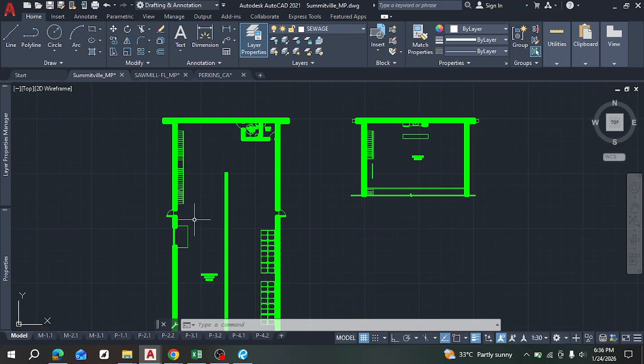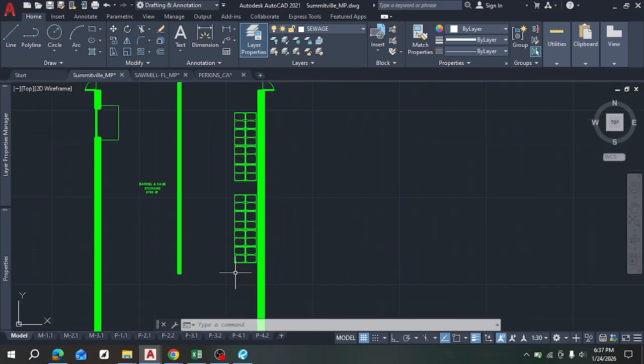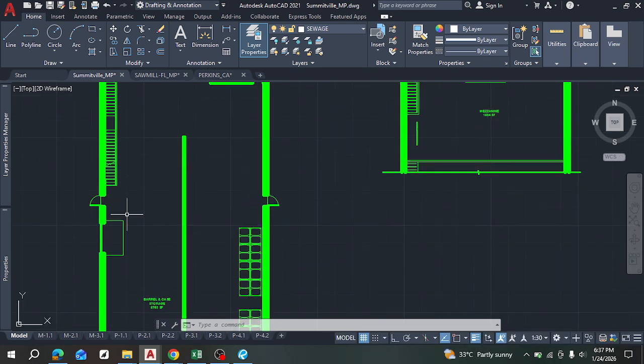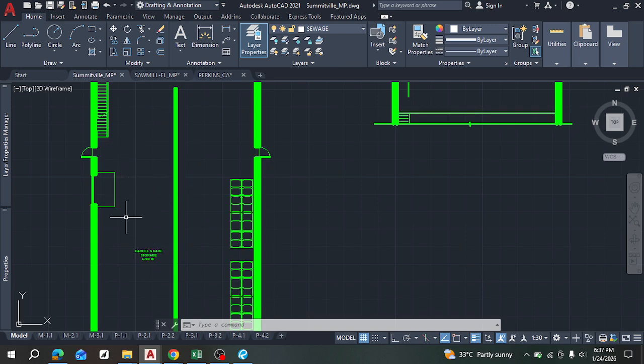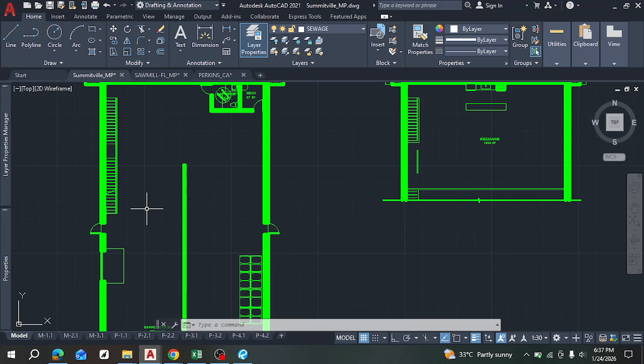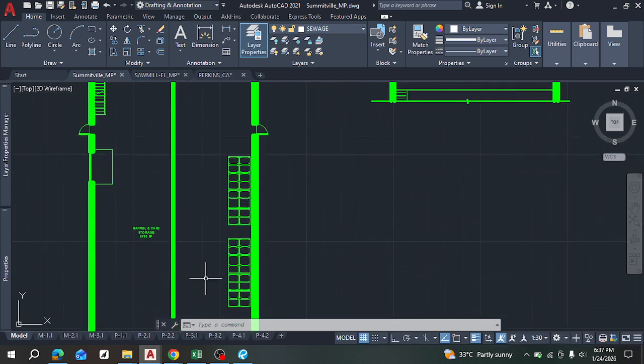Now I remember saying that floor drains are usually placed in rooms where there's likely to be a leakage, right? Or there's likely to be an overflow or spillage or something of that nature. So this is a storage or production space, right? And these are actually barrels. It's like a warehouse, a storage, a production, winery, all together in this space, right? So there's likely to be leakages in a lot of places. I'm going to add floor drains to a lot of places, right?